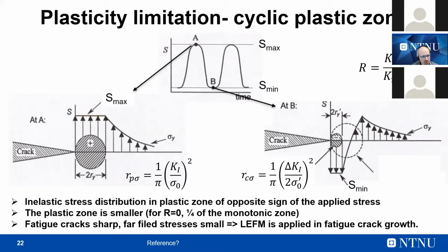So also here it is important to mention that in the fatigue case, we have a plastic area close to the crack tip, and we always have to verify how large this area is before making the linear elastic assumption. Usually, and I want to anticipate something of what I will say later, high cycle fatigue is almost always in elastic regime, and the small plastic radius that we have is much smaller than the process volume of the material due to fatigue. And so this means that, at least in high cycle fatigue, we can consider a linear elastic behavior for our material. And this will be shown when I explain better what a local approach is and how the local approach is applied for fatigue design.